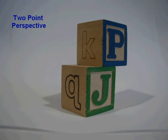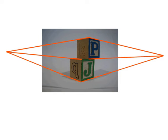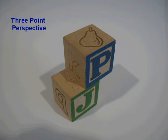In two-point perspective, the camera position is still level, but the object is rotated, resulting in views of two faces of the object. The horizontal parallel lines on the object are not parallel in the photo, but the vertical lines are. The horizontal parallel lines, if extended, all meet at one of the 2 points, hence the name two-point perspective. In three-point perspective, the camera is pointing up or down, as well as the object being rotated, and the vertical lines are not parallel either, so you get 3 vanishing points.